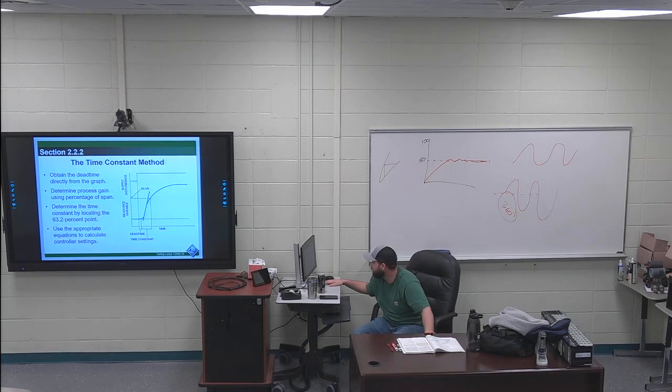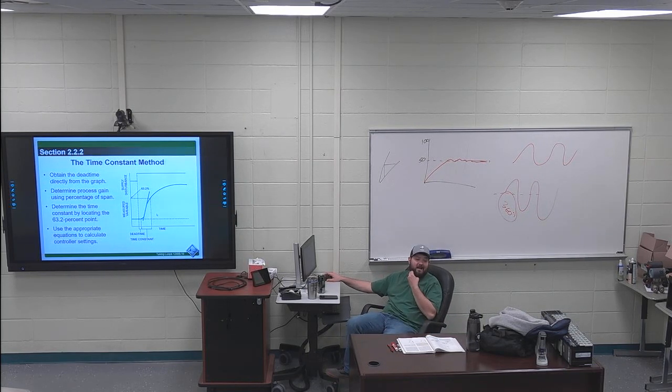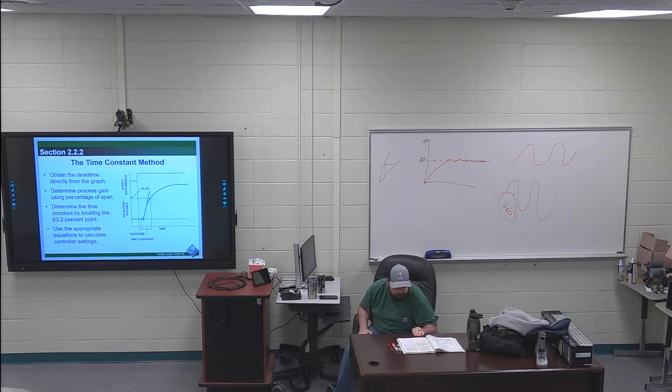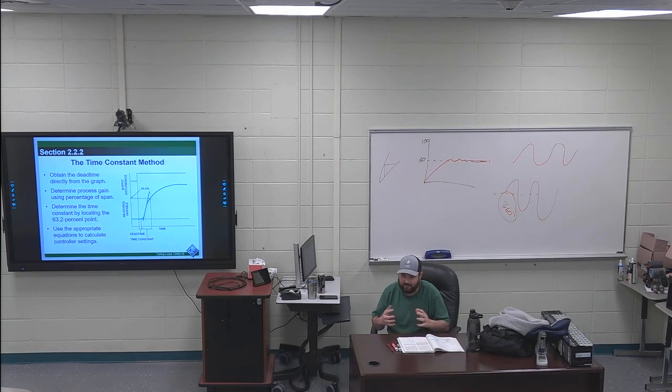So it is good to know, whenever I talked about dead time, dead time is kind of a buffer. It's just an amount of time that to us is nothing. But for a computer, it's like, all right, you made this change. Is this really changing right now? And in literally a blink of an eye, it determines, yes, we are. So then your variable will start changing. Yes, we really need to open up this valve. It's not just a blip or something like that. So think of dead time as kind of a buffer or a lead-in time.